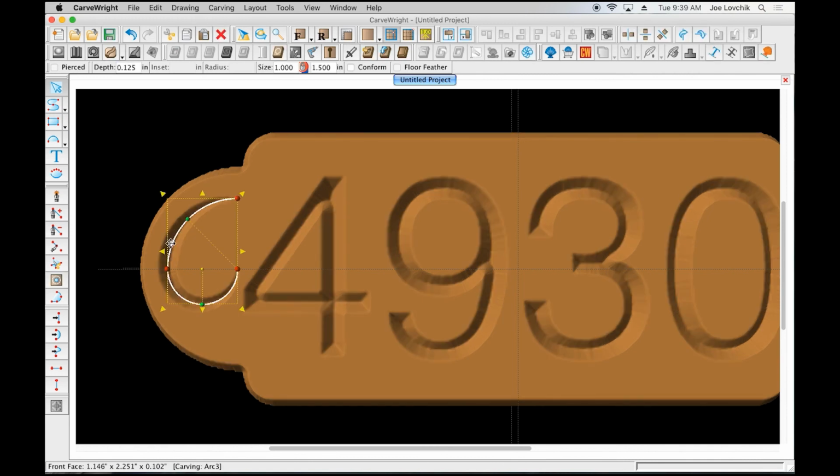So you can actually do some neat carving techniques and little decorative pieces here and there with this tool. There's one other tool that we didn't talk about on that drawing toolbar, and that's the route tool here. And this is used with these select depth profile pieces here. When you click on that tool, it actually allows you to change the center point of that profile.